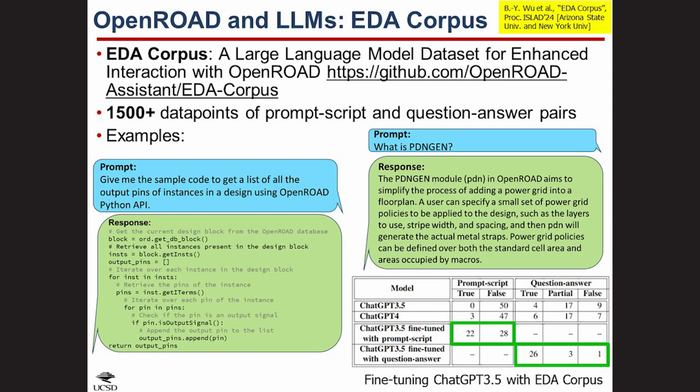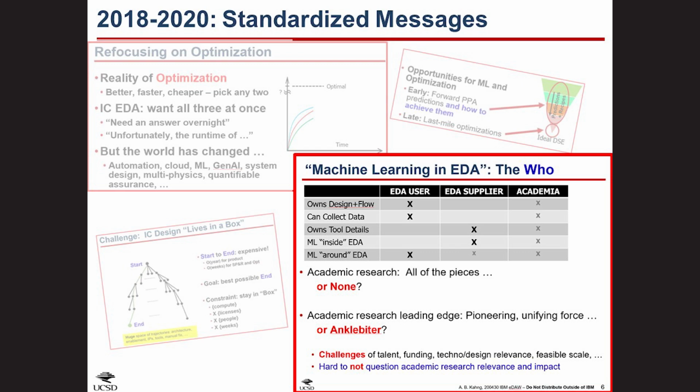Finally, optimization strategies can do more in a given unit of time because there's multiprocessing and the cloud, if you're not limited by the number of copies of runs that you can launch. So here's what my students and I call tomography. In this case, run the early global router a bunch of times on a placement to get a very rich set of images. Each run takes less than a second, and you can do them all in parallel. Then set up your expensive detailed routing run with a learned model or an inferred set of routing blockages based on this rich information.